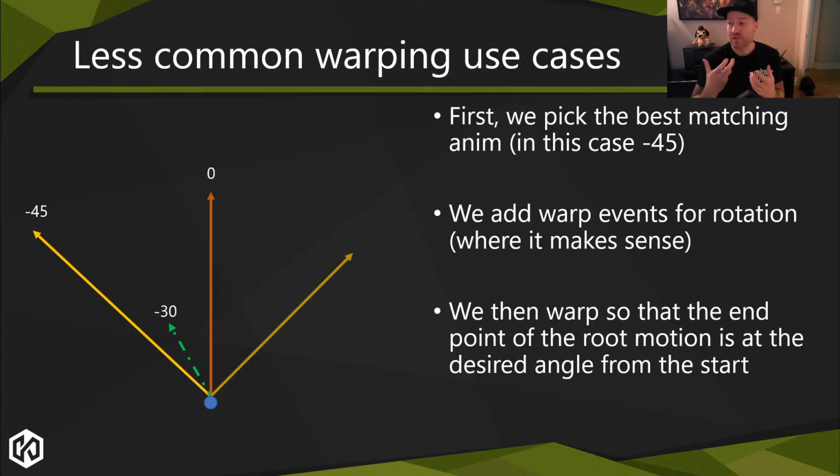Then what we can do most of the time, especially for starts, is rotate and then move, right? Because we're standing idle, and applying the rotation initially and then moving is less ugly than applying it during the move. Additionally, it gives you a more accurate result because you haven't moved. You're just rotating and you're going in the right angle.